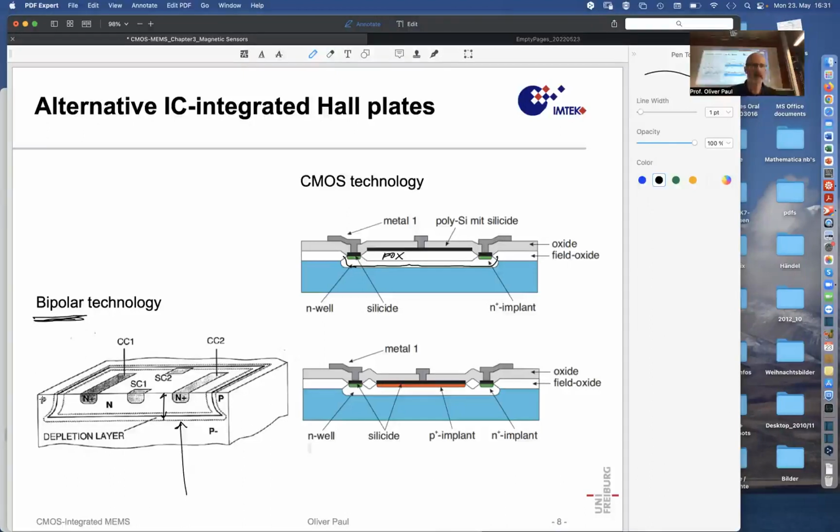So this is again isolated all around by a PN junction that is neatly shown here in both regions, with the metallurgical transition indicated by the solid line. That's where ND is equal to NA, just at this line. And here ND prevails, and on the left side NA prevails.